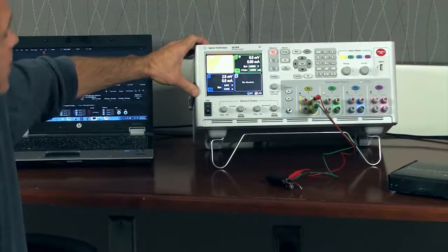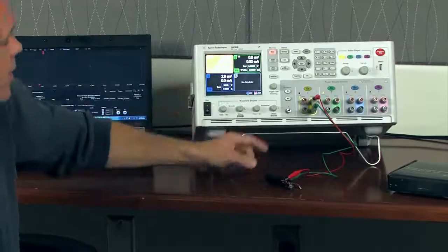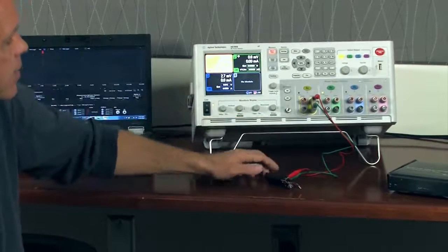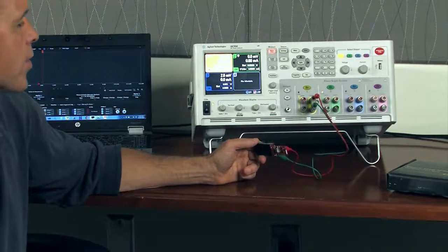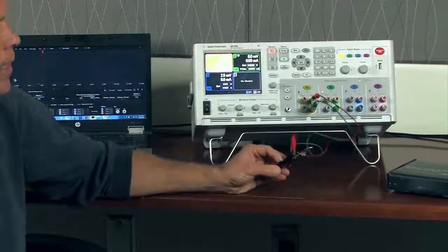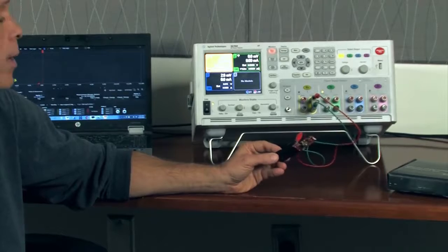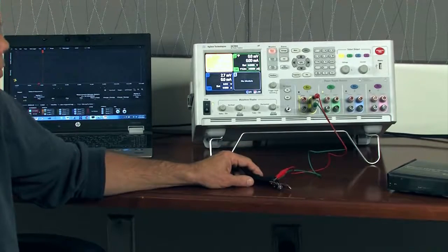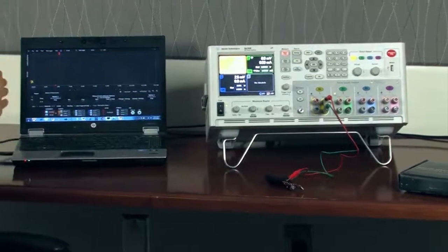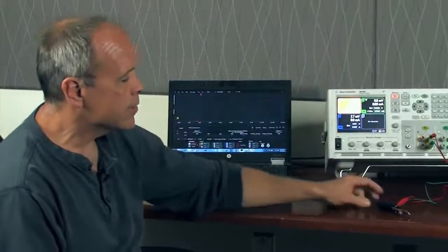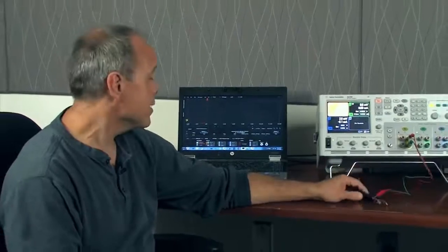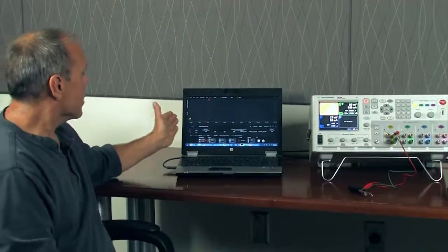DC Power Analyzer. And what we have here is the analyzer hooked up to the MSP430, and it is simulating the battery. These things are powered by batteries. And so to run the test, we're going to start the data logging software, and then I'm going to use this analyzer to simulate the battery to turn on the processor, and then we're going to collect current readings, and then we're going to analyze those current readings when we're done.